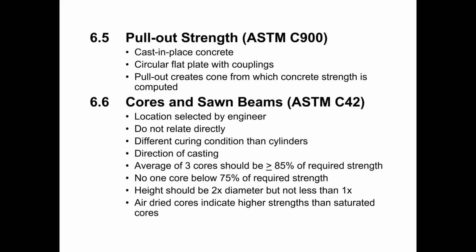All right, that is their prerogative to do that as the owner of the project. So just be aware, if it is a DOT project or other government agency, that they may have their own specification and they may require that cores achieve 100% of the required strength.